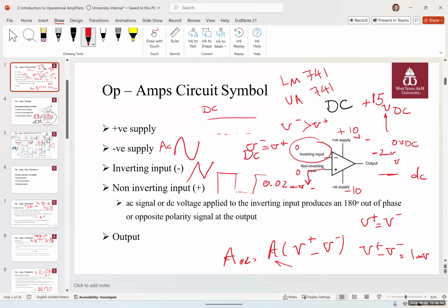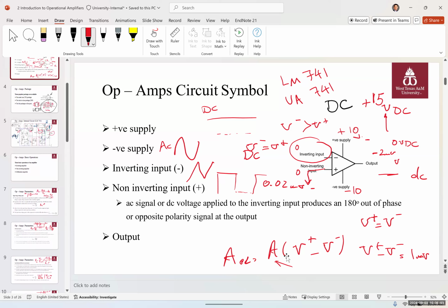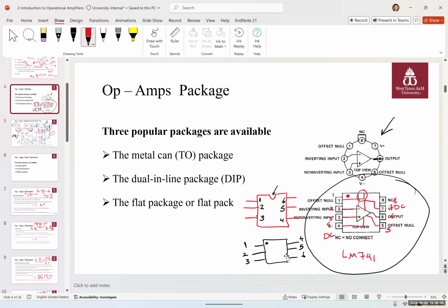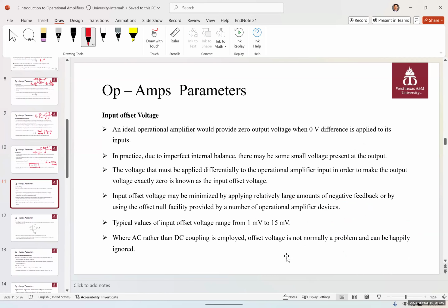And sometimes they're not balanced, so you put a small weight on one of them to balance that. This is exactly the same that we do. So some op amps, like the 741, have dedicated pins and terminals for the offset, and you add these together with a potentiometer, and you tune the system so you would have 0 volts on the output. So before giving any signals to the input, you would balance and actually offset that voltage to have a 0 volt in the output.